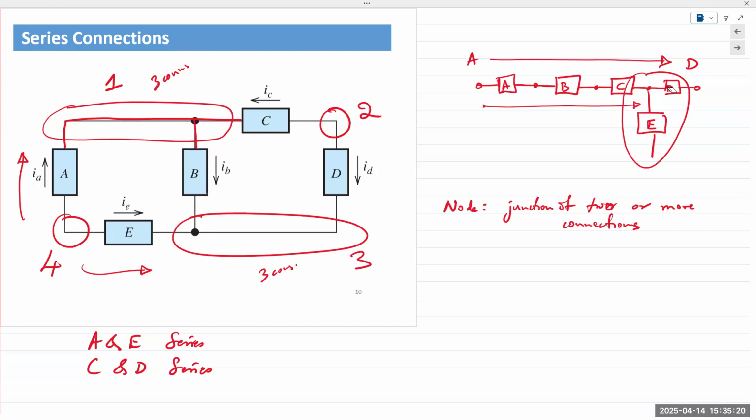If the other end of that component is not connecting to anything, it's left open and unconnected, then the circuit behaves as if it's not even present. Again, if a component is connected anywhere in a circuit by one terminal and the other terminal is left open and unconnected to anything, then that component may as well not be part of the circuit at all.